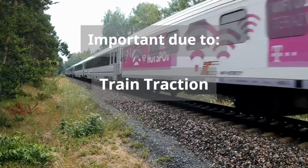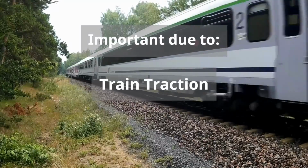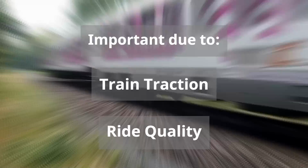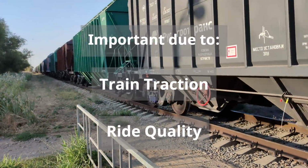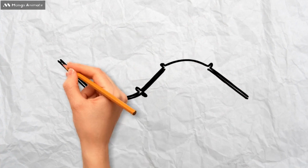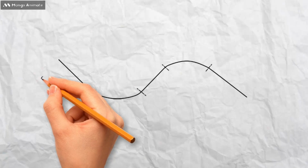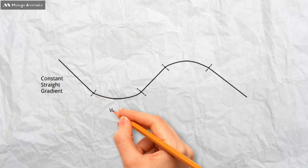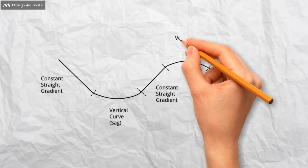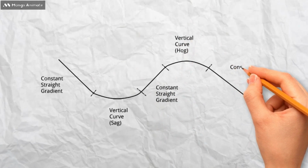Another reason vertical alignment design is important is for ride quality for passengers. We don't want them to feel like they are on a roller coaster. Similar to horizontal geometry, vertical design consists of a series of constant gradients and straights. These are joined together by vertical curves. In vertical design we do not have transitions.